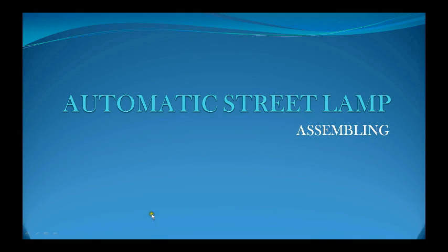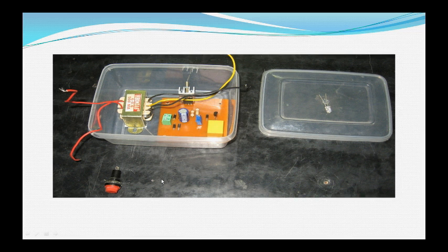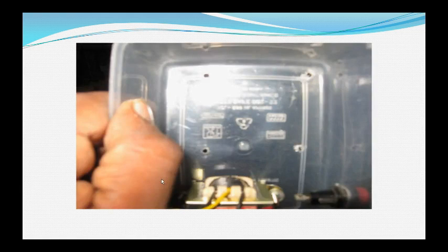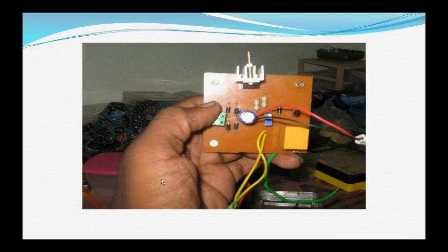Let's move to the final stage of the project, the assembling. The first stage of the assembling is to mark the positions of the components so that we may drill holes and fit them. First I attached the fuse holder, later I attached the transformer and drilled the holes for the PCB.